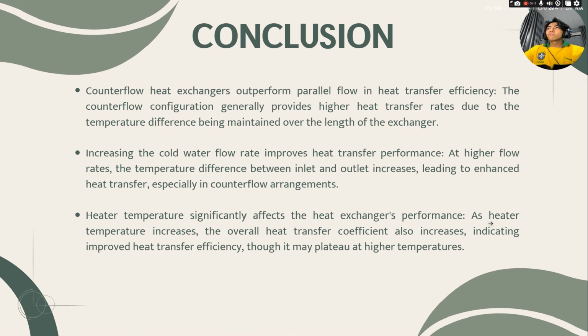I'm going to explain the conclusion for lab 5. First, counterflow heat exchangers outperform parallel flow in heat transfer efficiency. The counterflow configuration generally provides higher heat transfer rates due to the temperature difference being maintained over the length of the exchanger. Second, increasing the cold water flow rate improves heat transfer performance.